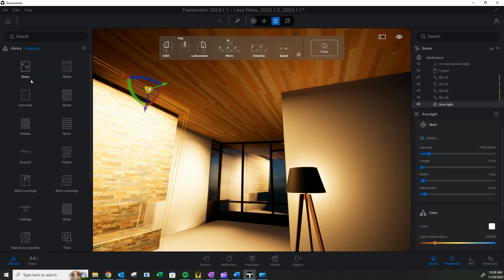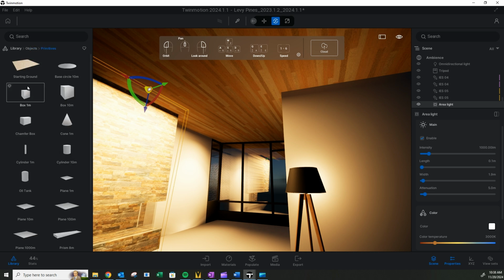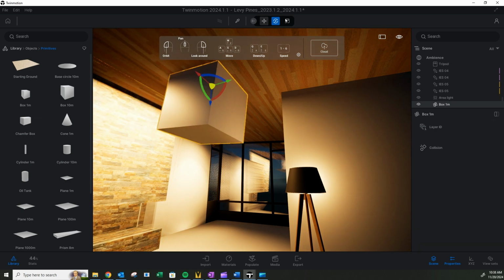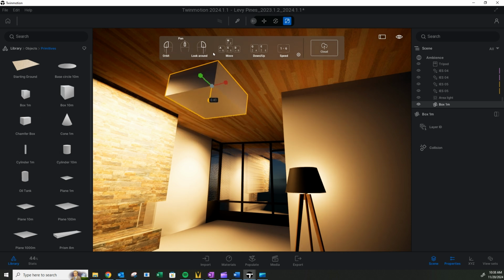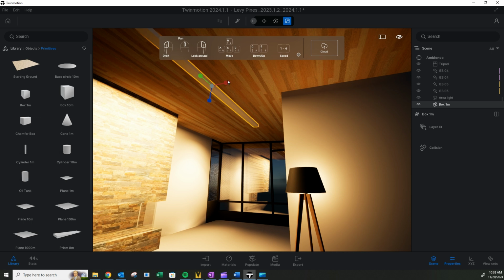You could also do, nowadays, LED tape light. You could do just about anything, I feel like. But you would want something with higher output, and you would want to put a lens over it instead of a shroud, to make it a lot softer. You could do a very narrow line of light, but you can almost do like 1,000 lumens a foot and spread it out a little bit.